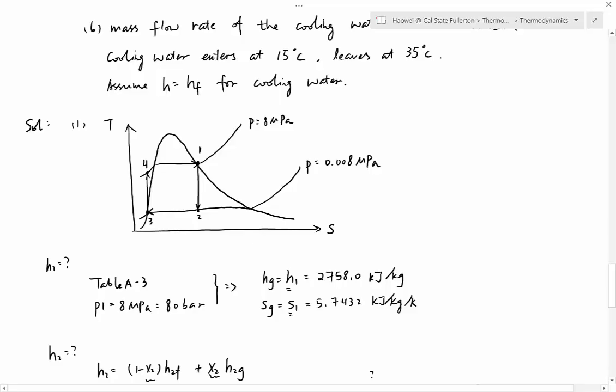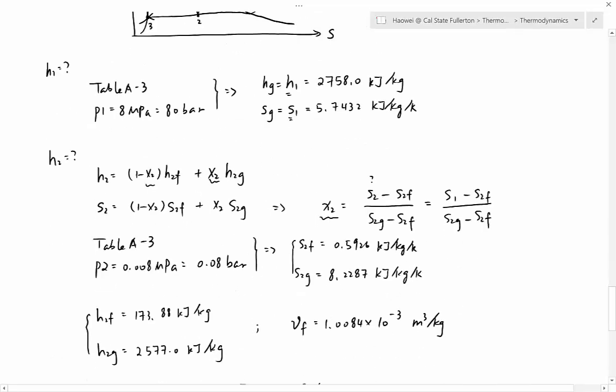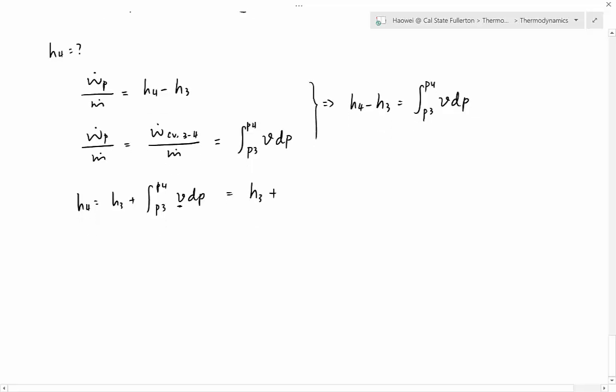If it is liquid, we can usually say the density must be constant. And what is my integrand? My integrand is specific volume. What is specific volume? Specific volume is the inverse of density. So if density is constant, nu must be constant. If your integrand is constant, you can pull it out. After you pull it out, you can give the subscript. You can call it either nu3 or nu4. It doesn't matter because it is constant.